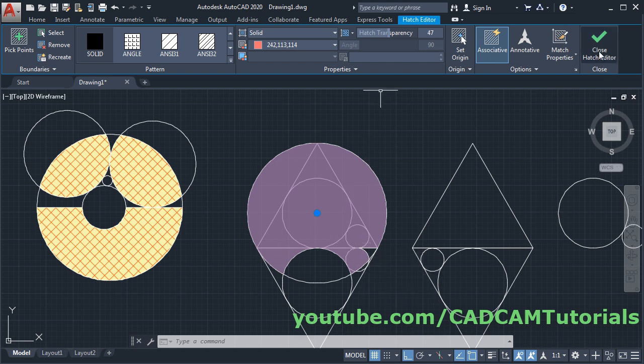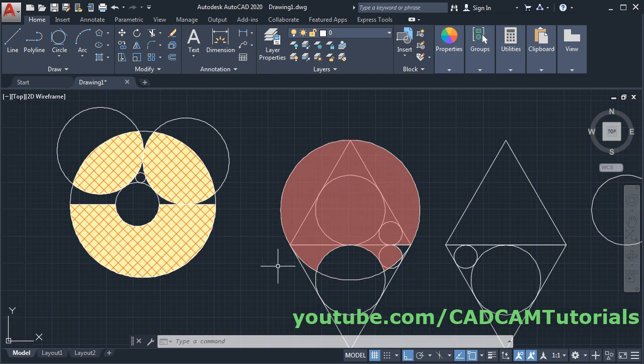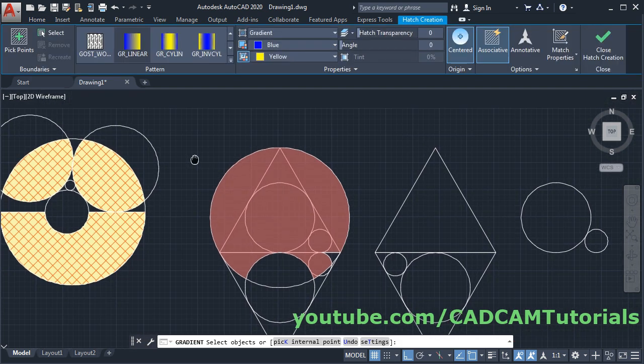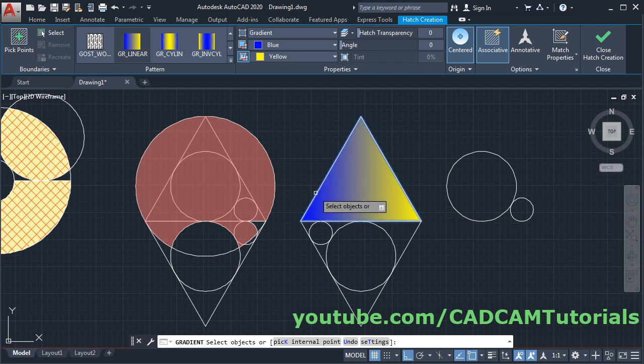Click on OK. So in this way you can make your hatch transparent also. Same way, if you want, you can give gradient hatch also. For gradient hatch, click on this arrow and click on this gradient. Then right now our select object is on, so I will select this object.